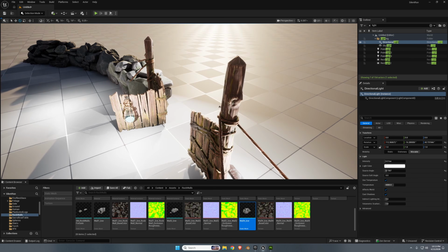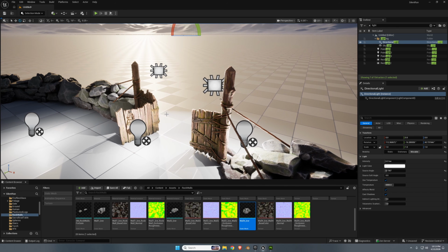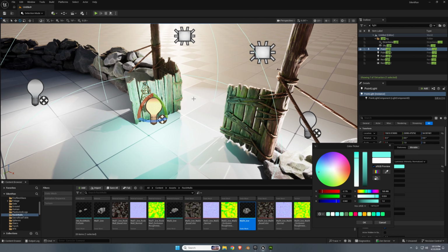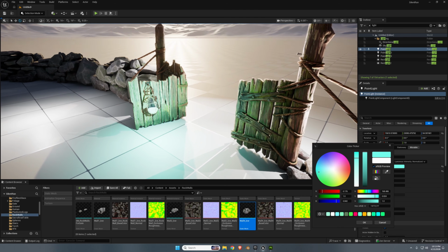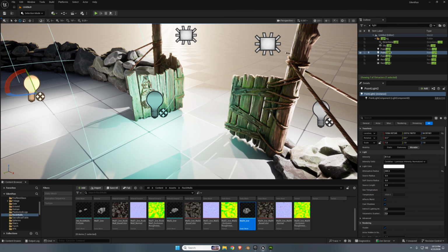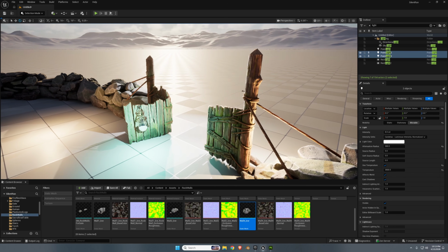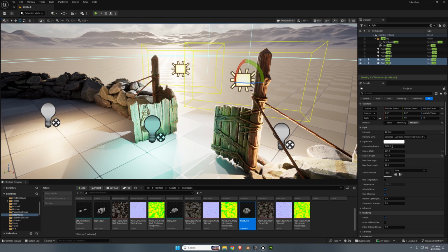And yeah, okay, let's see. Maybe we can change some color settings here, make this a little bit more bluish since our liquid from the get-go is blue. And the other ones I'm gonna make warmer, so we also create a little color contrast. We're just gonna select multiple lights, the point lights that you see here. We're gonna use the temperature and we're just gonna move it to a smaller number, maybe 3500. And for the rim lights, we can see if we want to change them later, but I'm gonna make them colder for now.